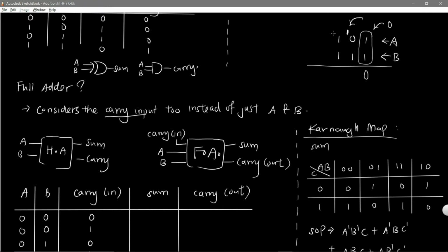So 1 plus 1, it carries to 1 again. And this here is 0. So again, this here has a carry of 1. But now A and B are both 1s. So you have 3 inputs of 1s. So now you have another carry of 1 to the other place, but now the sum here is 1. And then you have 0 and 0 for A and B here. Just the carry of 1, so this is 1. So 0, 1, 0, 1 plus 0, 1, 1, 1 equals this number, right?